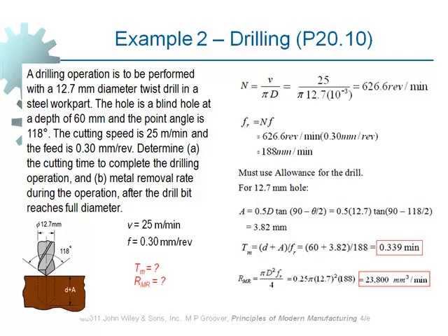So you see, equations are very similar in conventional machining operations. There are small differences in some of the equations, but most are similar. The cutting speed and spindle speed relationship is always the same, it doesn't change. The difference in the cutting speed equation is that instead of substituting the diameter of the workpiece for capital D as in turning, here the diameter refers to the diameter of the cutting tool.